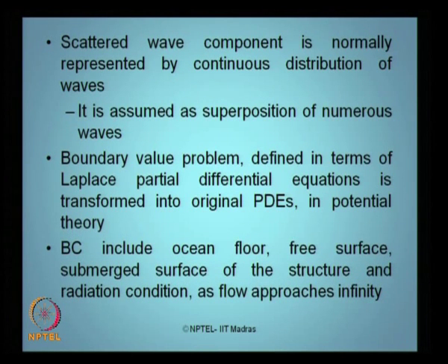Now the question here is, where are the boundary conditions? The boundary conditions include the ocean floor, the free surface, the submerged surface of the structure and the radiation condition as the flow approaches infinity. These are the boundary conditions I apply for solving my potential flow theory.